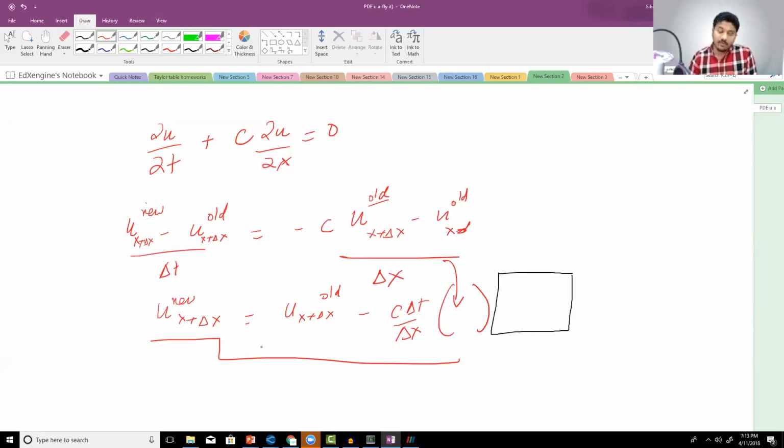Similarly, if you have additional equations like the continuity equation, momentum equation, energy equation, you can follow a similar procedure. This procedure is what people call a solution algorithm. And at the end of the day, you will always end up with a matrix, which is called a linear system. To solve the matrix, there are several methods. These are called linear solvers. And when you solve it, you get your answer.